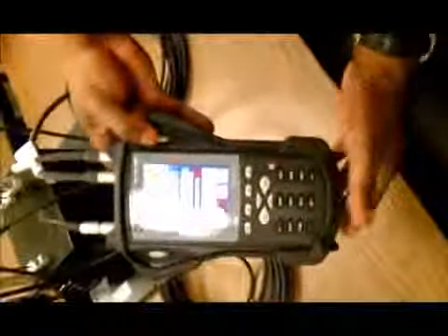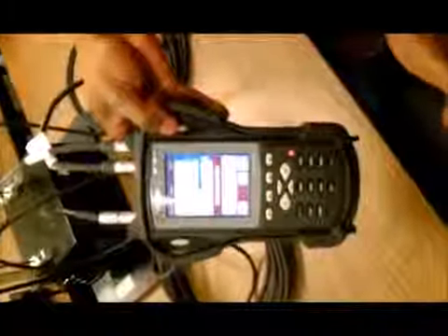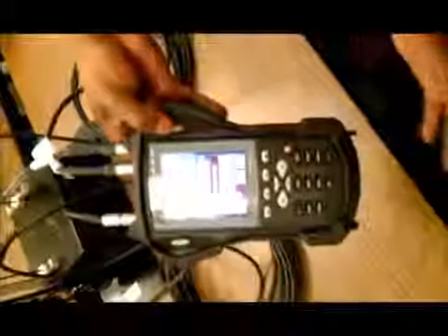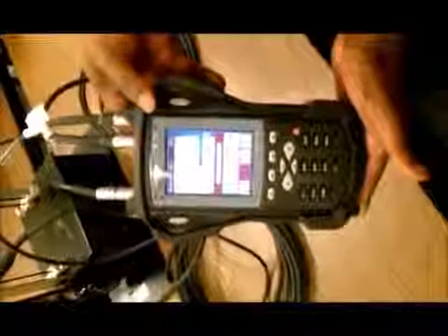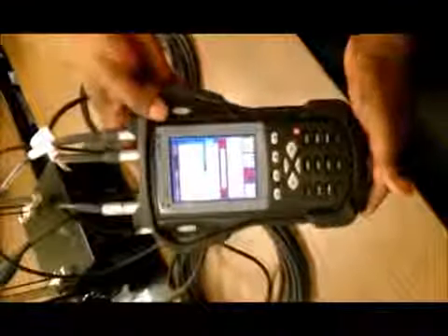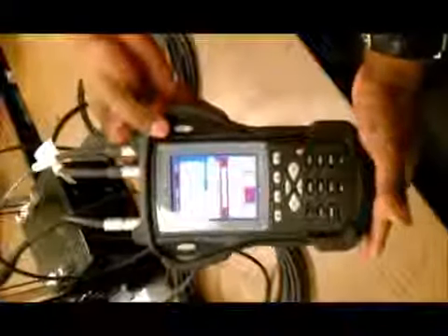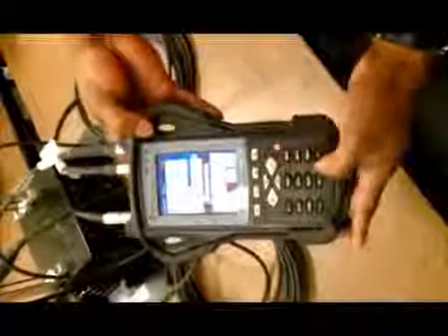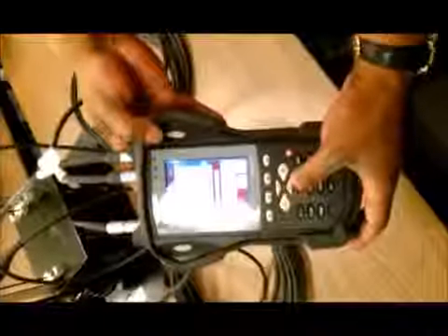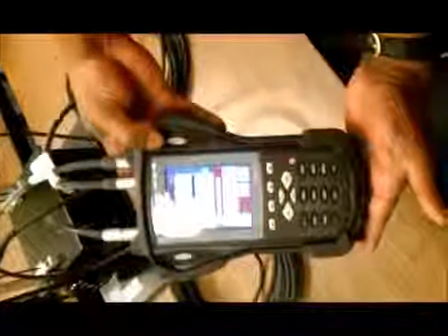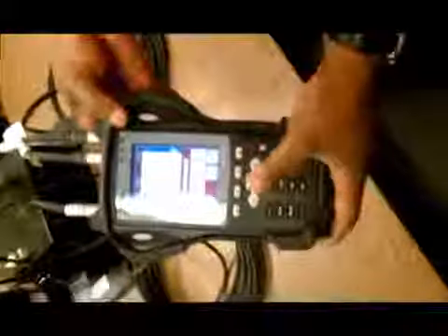And our frequency range is the maximum amount that we'll look at. In this case, we'll put it at 3,000. This instrument right here is capable of 40,000 CPM, or 40,000 Hertz as the maximum. So we'll change this to 3,000. And the resolution, we can change that. We have 100, 200, 400, 800, 1600, 3200, 6400, and 12,800. We'll leave it at 400 lines because it's still high resolution, but it doesn't take as long to get the readings.